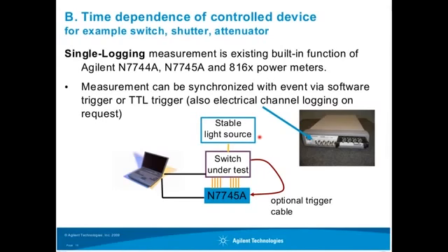Okay, and again, we want to have stable light sources if these are passive components that are just passing signal through them. One more point I'd like to mention: we do offer on request this kind of power meter also with electrical inputs, and that can be interesting in some cases for looking at how the optical signal changes with a direct time reference based on an electrical control signal, for instance. These are current meters actually and can be used to monitor photodiodes.